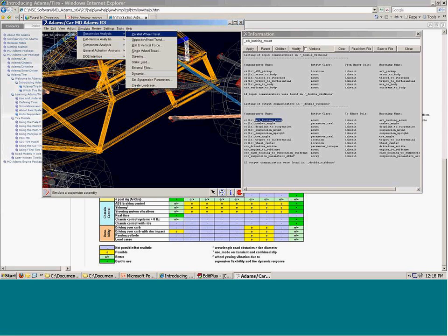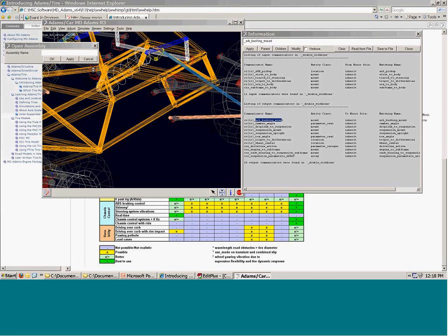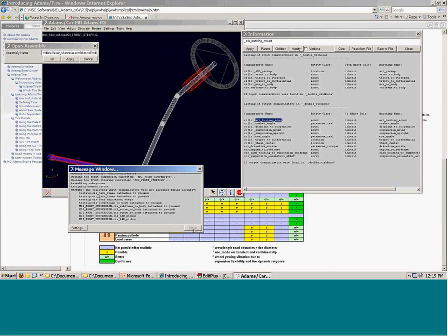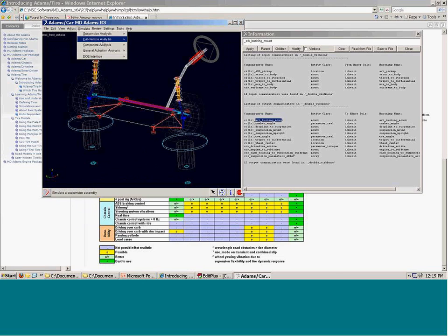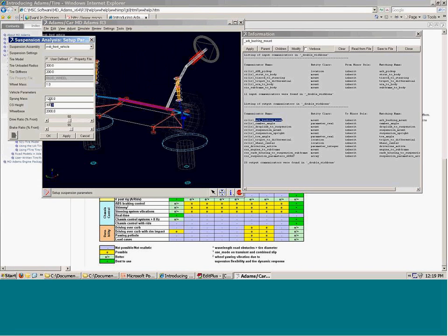I didn't go into it, but if you open up the suspension assembly, to mimic compliance of the tire, you have the tire unloaded radius and the tire stiffness. If you use a tire property file, it still picks up these two things as the quantities to apply the tire force when the contact patch is excited.